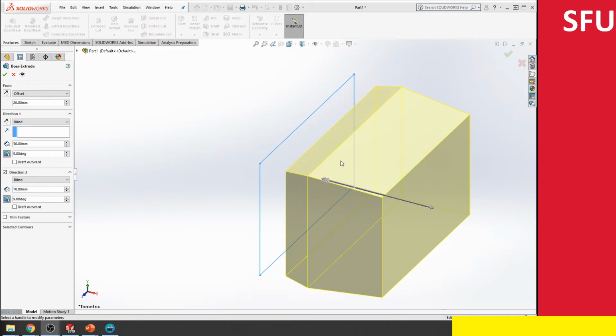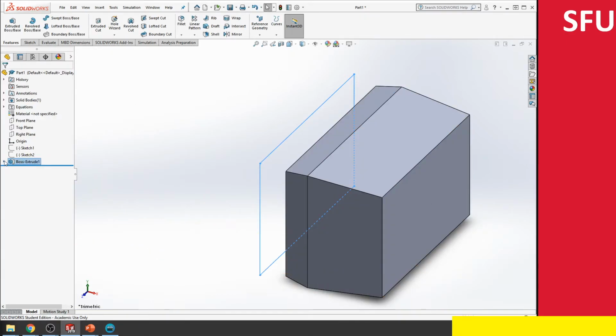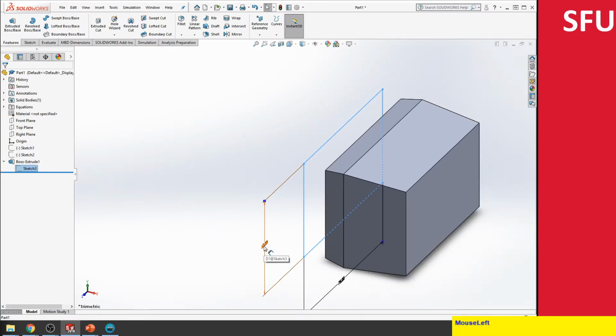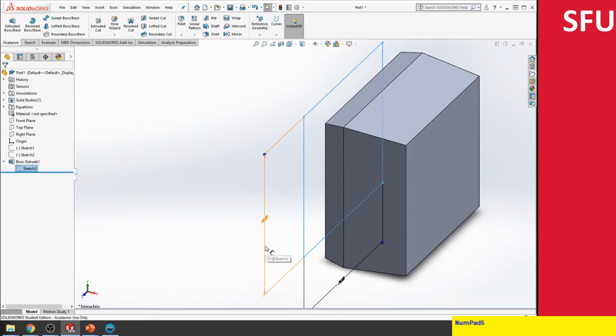So we can give the draft in either direction and then change the values. Once we do this, we can say okay, and this is the part. Now notice that the sketch has gotten hidden. If we want to change the sketch, you have to drop down and click. Some of the dimensions will be visible here that you can change. For instance, instead of 50, let's make it 75, which is significantly bigger. Now notice that the cross section has become squared,